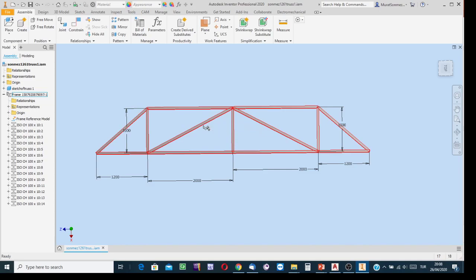Okay? Correct. Because I said to locate the member, coincide the member's center line onto the existing skeleton. Since I created the skeleton using the true angles, the created truss uses the same angles, and the inclination and orientation of the members are all correct.